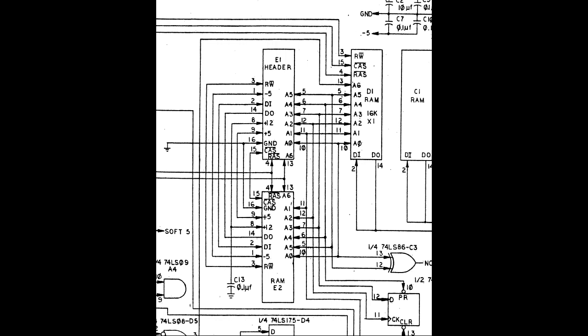So the card designer cleverly used the refresh and the multiplexing from the motherboard, but they needed to bring the signals to the board because they are not present on the expansion connector, to refresh and multiplex addresses on the RAMs. They thought to extract one chip from the Apple II motherboard, and get to the needed signals with the ribbon connector and the header.